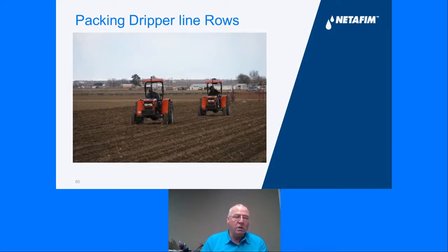And the third thing it does is it eliminates as many of the voids as we can around that dripper line, so that water will move back to the surface as quickly as possible. It's an essential part of the installation process. We recommend it on every project that we do.